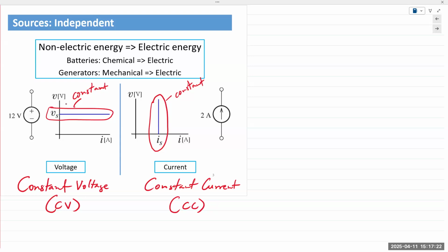One of the most common ways to do that is to first set a current limit, so that the current shouldn't increase beyond a certain point. For every experiment you perform going forward as an E, always keep in mind, you must set the current limit for your procedure.